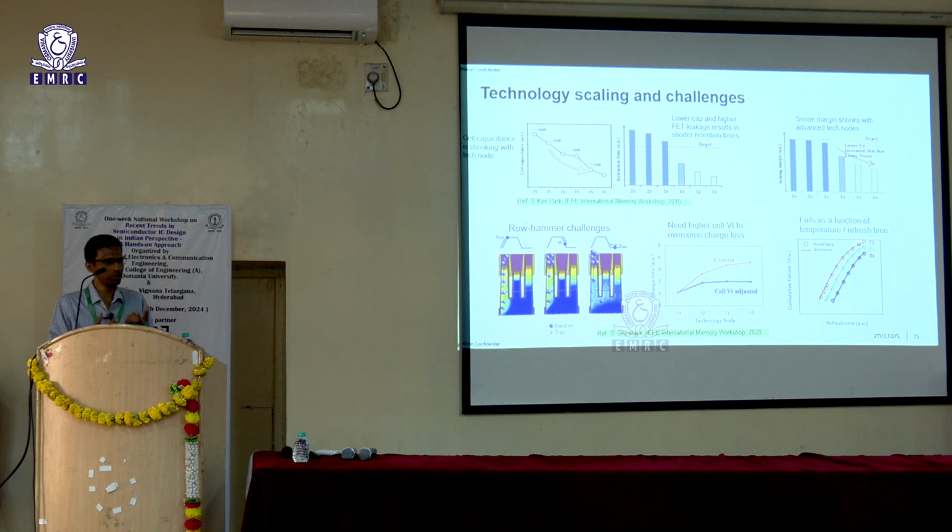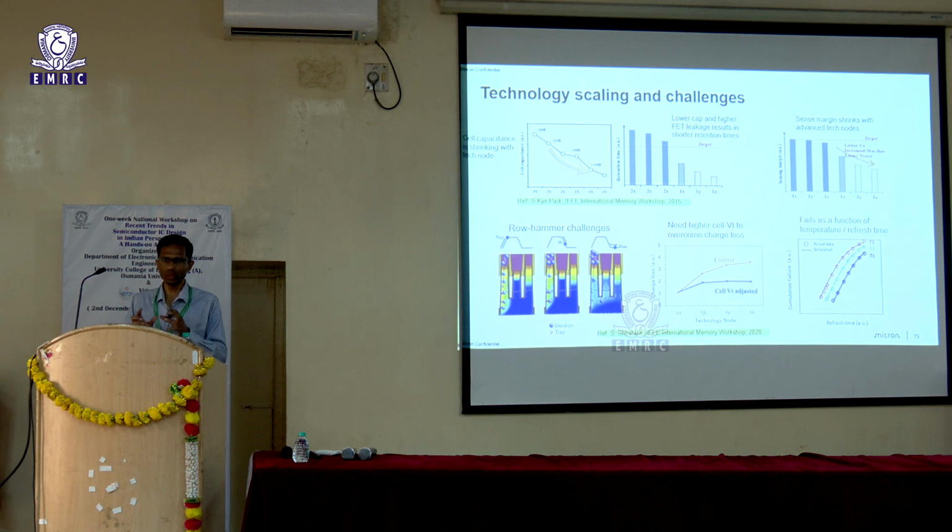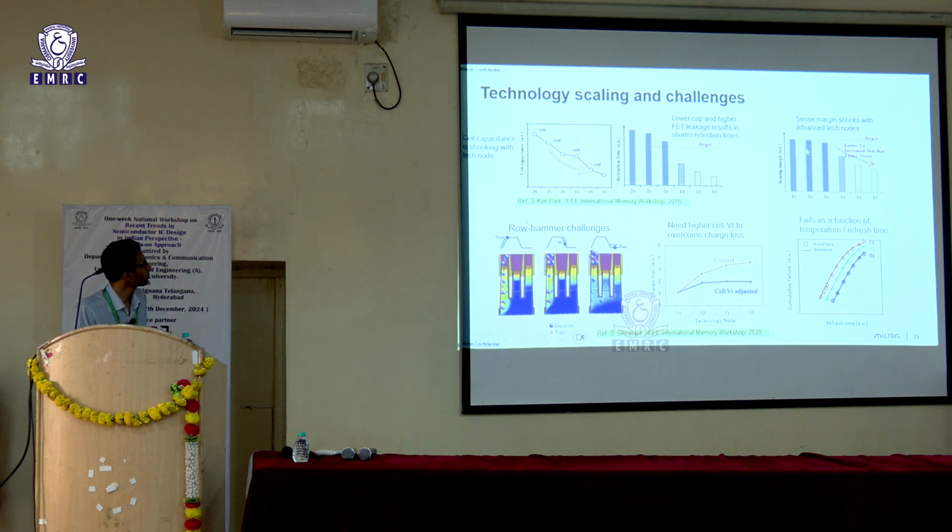So in the earlier example, we had 150 millivolts of data information being fed to your sense amplifier. Now it could just be, say, 100 millivolts or even less, 75 millivolts. So your sense amplifier now has to resolve that smaller amount of delta. So it essentially translates to sense amp margins. So sense amp margin is going to get lower and lower with technology.